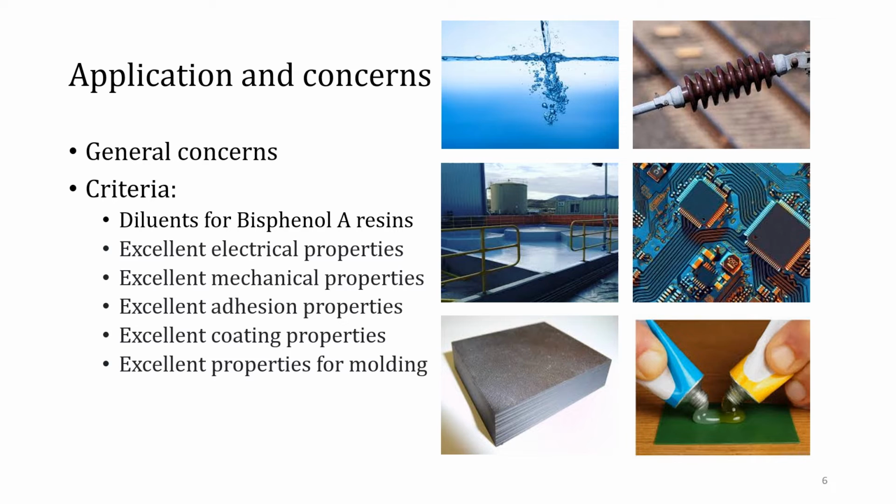The cycloaliphatic epoxy resin used as a coating is also distinctive in the application of coatings. With this kind of resin as the base material of the coating, the product can be high temperature resistant, such as more than 300 degrees Celsius. The cycloaliphatic structure imparts surface resistance and leakage tracking resistance to the electric coatings, which contributes to the color retention and durability of the outdoor coating.